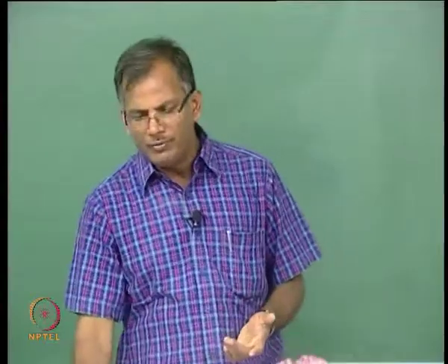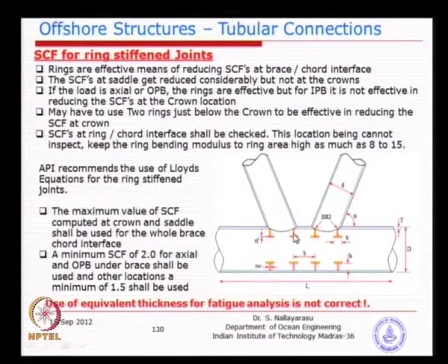Whereas here, we need to make sure that the stress concentration between the chord and the stiffener itself, inside somewhere here at the inner face, is not governing the design, because you always have the stress concentration factors calculated for the brace and chord interface. But if you forget the stress concentration factor inside the chord, you may actually initiate a failure in that particular location.